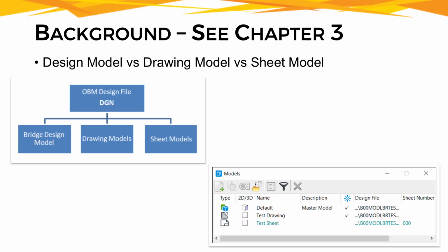While you can have as many models as you'd like, we generally recommend to have the design model where the 3D model lives in a separate DGN file and create a separate sheet file to reference a 3D model into. This has two main advantages.